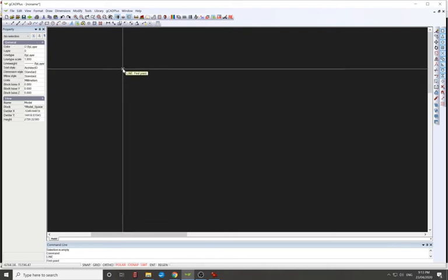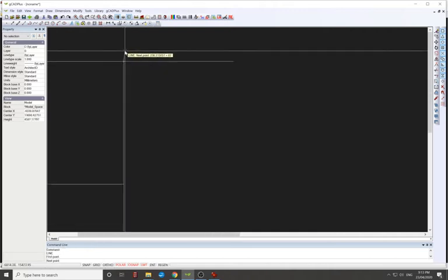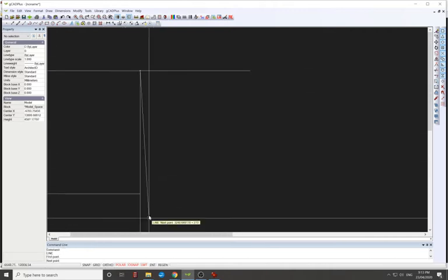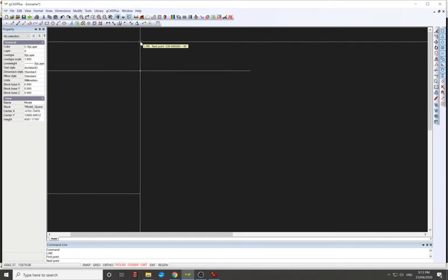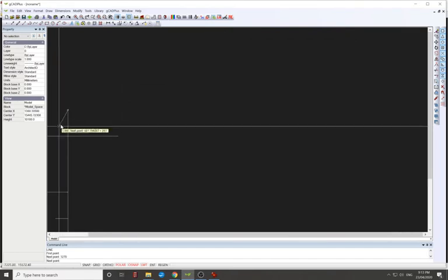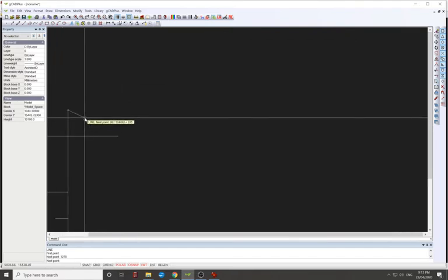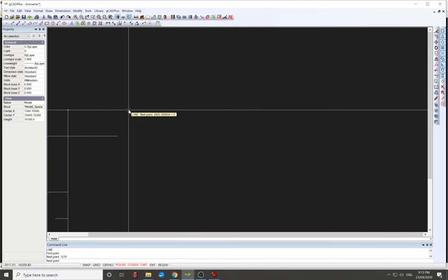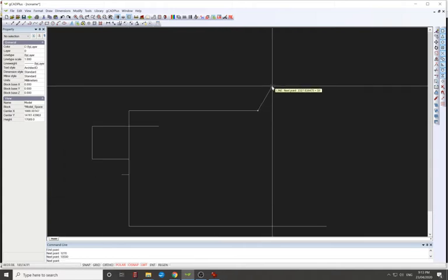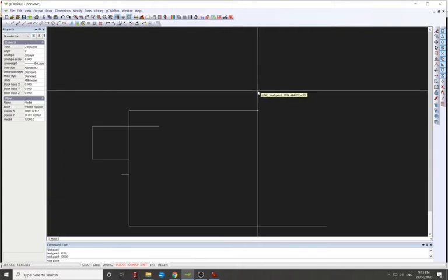Then I just press enter, start a new line, instead of going line, etc. And this one, you'll see it's that 1270 again, which we had on that side there, and that's to the corner of the house. So lock it in the polar tracking, put the distance in, enter, and that's what we have. Now the sideway is 10,500 millimeters, 10.5 meters. Enter. Go back this way. This sideway. Have a look, I can't read it.